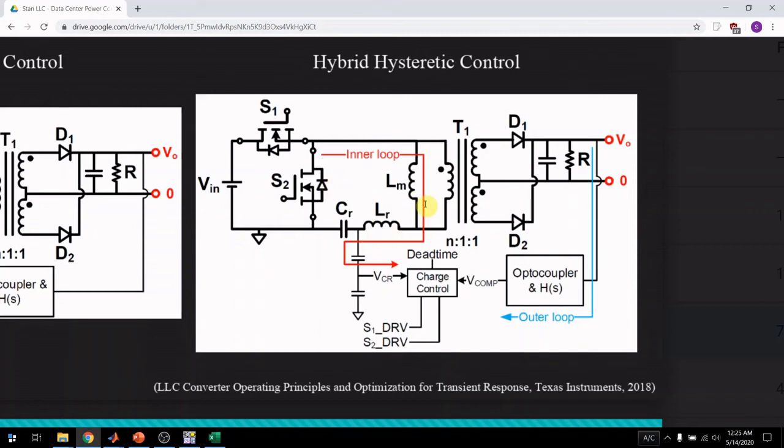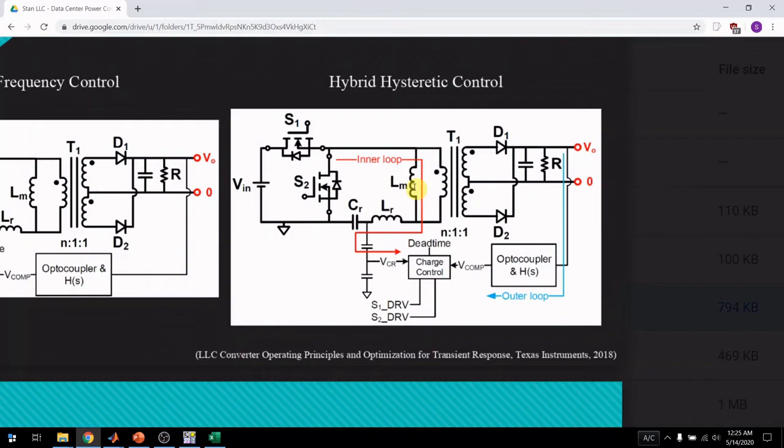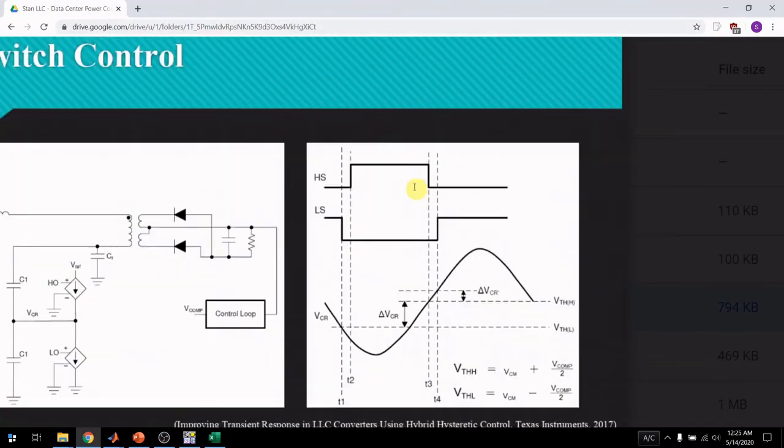So you can actually have features like ZCS avoidance, where the chip knows whether you're getting into that zero current switching region and makes sure to stay on the right side of that peak that I talked about earlier. You can also control the gates independently, so they have adaptive dead time, and they give the gates just as much dead time as they need to discharge the capacitance across them.